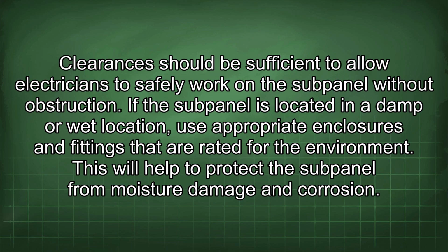If the subpanel is located in a damp or wet location, use appropriate enclosures and fittings that are rated for the environment. This will help to protect the subpanel from moisture damage and corrosion.